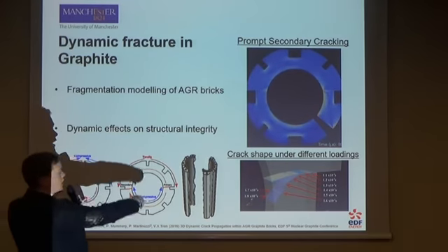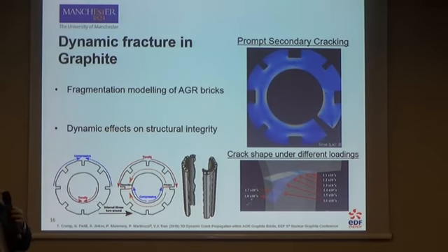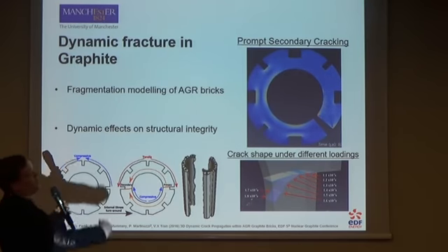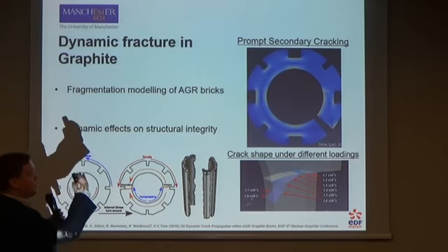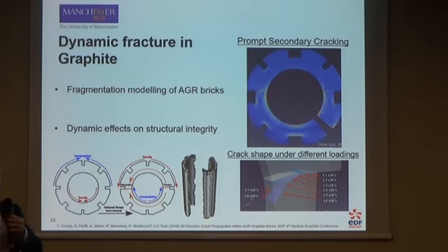We can look at a crack shape which is close to the fracture criterion, which is very equivalent to the quasi-static shape we've seen with just a standard external approach, under a lot larger loading, which gives us an interesting interaction due to K1, K2 and K3, and in particular what I wanted to look at, which is further fragmentation of the component, i.e. secondary cracking due to strain rate. And it's really key to note that the quasi-explicit solver is useful for this because the waves we produce from the initial crack are energetically conservative, so therefore we can look at possibly some initiation secondary to that.